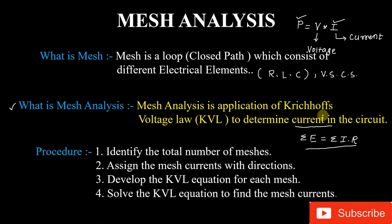Now, when we apply mesh analysis, there is a certain procedure. In the first step, we identify how many meshes are in the circuit, which means we find how many loops or closed paths there are. In the second step, we assign a mesh current to each loop with a direction. I preferably use this direction, which is called the clockwise direction. We can use the anti-clockwise direction also, but clockwise is the best direction to understand mesh analysis.